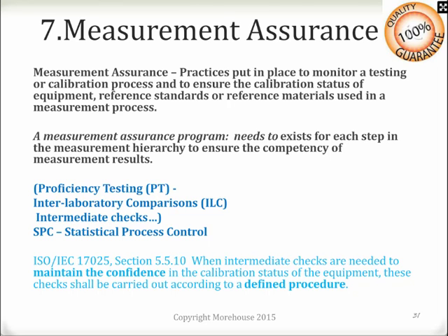Intermediate checks, SPC. SPC is statistical process control. In fact, we believe SPC is so important that we offer a full-day class on it. This is something you can use to monitor what's going on in your laboratory. If you happen to have an out-of-tolerance condition, SPC more than likely is going to tell you when the artifact was last good. So if on Sunday I check my artifact and it's good, and on Wednesday I have an out-of-tolerance condition, now all I really have to do is look at all the calibrations performed between Sunday and Wednesday, instead of having to look back on a year or maybe 2 years of data.